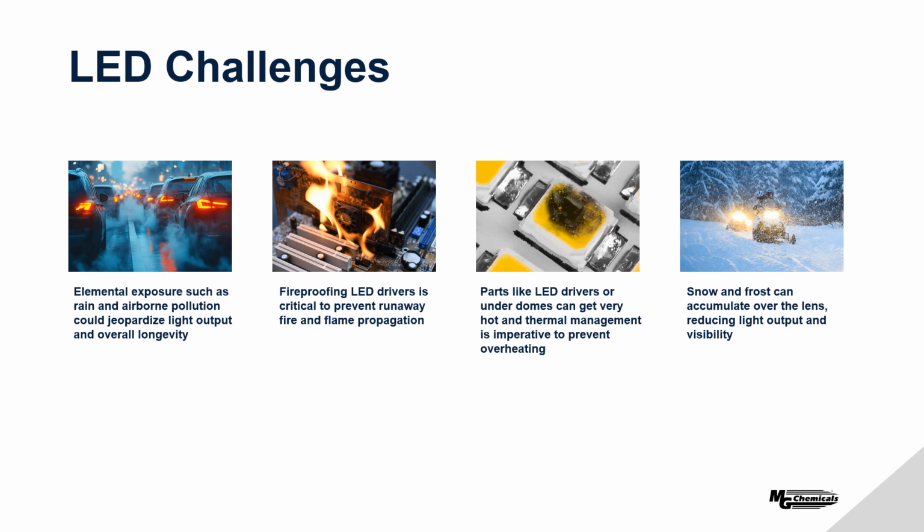So that is basically a fail-safe should the driver catch fire. A lot of designers now are looking to put in materials that will not propagate flame and spread the fire. Staying on the subject of LED drivers, they also get very hot during operation. So thermal management becomes a critical issue to prevent the bulbs themselves from burning out. And then lastly, we have things like snow and frost, which can accumulate over the lens, and this will subsequently reduce the light output and visibility. So those are the challenges. What kind of solutions do we present?